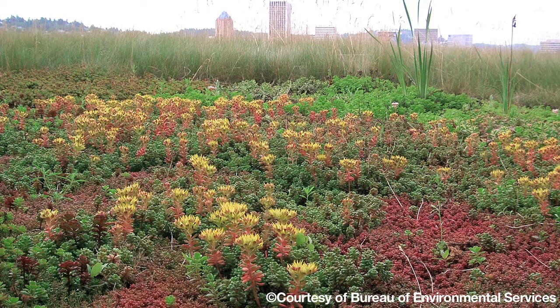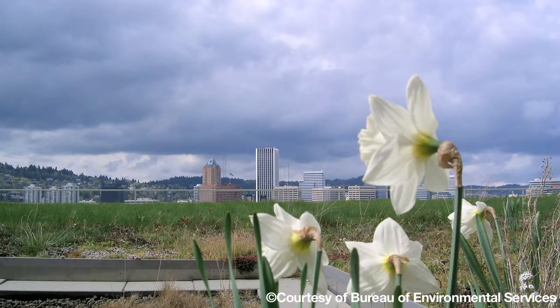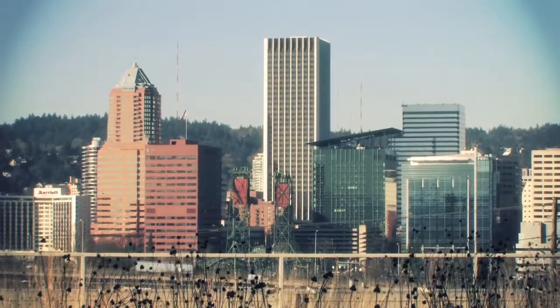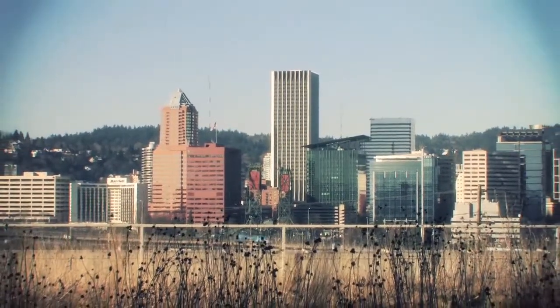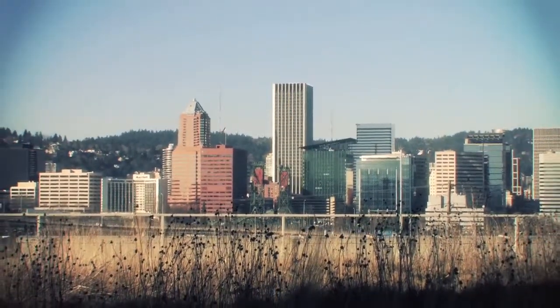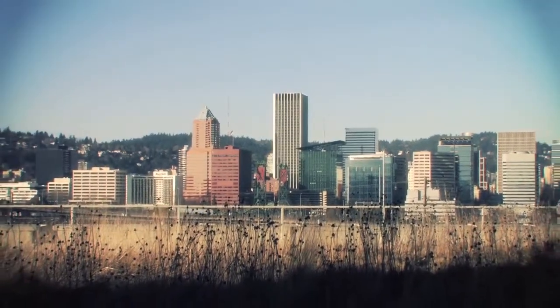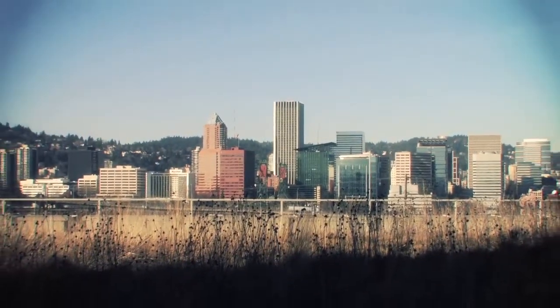The project designers selected plants according to criteria that included adaptability to roof conditions, ecological function, local availability, drought tolerance, aesthetics, and maintenance requirements. Portland's extensive summer dry periods made an irrigation system a requirement. The permanent drip irrigation system is 3 inches below the surface of the soil and delivers water directly to the roots. Soil moisture sensors control the drip irrigation system.